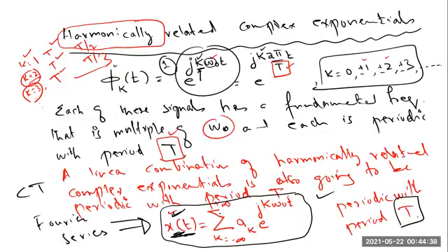So for any periodic signal, when you expand this summation operator, you will get a number of terms. You will get a constant term for k equal to 0. Then you will get the fundamental component or first harmonic component. Then you will get the second harmonic component, third harmonic component. So depending upon the value of k, this expression will give us a number of components that we call harmonic components. So for periodic signals, we always use this terminology of harmonic components for the different components present in the signal.